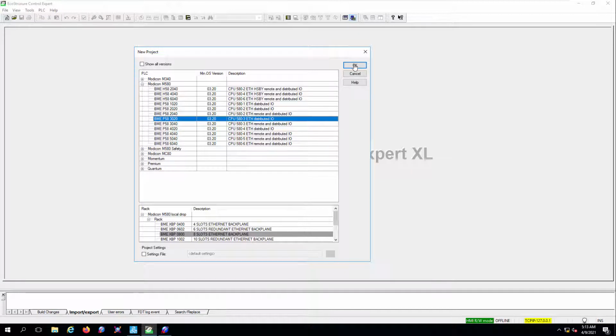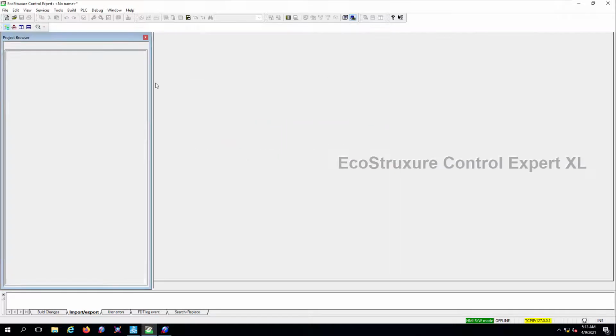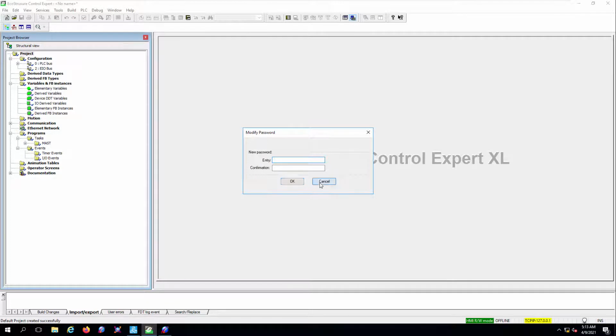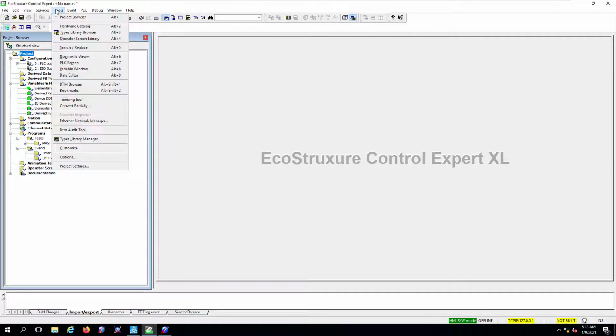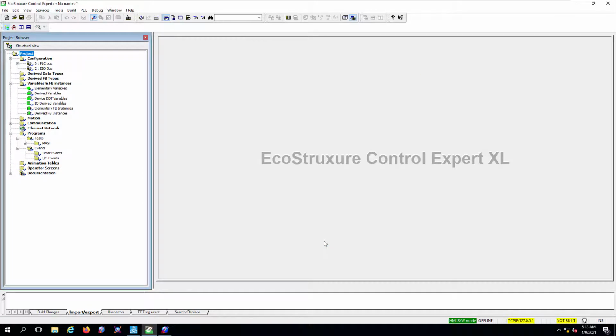We will start by working on a new PLC application, which will be for an M580 controller. In the project settings, we enable the data dictionary to communicate with the Modicon communication server, which gets data from unlocated variables in the PLC by means of the UMAS protocol, and then makes data available to Aveva System Platform via OPC UA protocol.